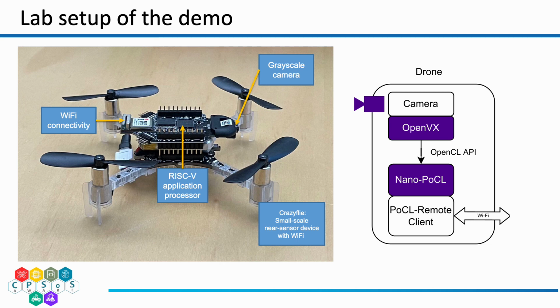The whole application logic is executed on the RISC-V core on the AI deck. The application consists of an OpenVX program implemented in OpenCL. The Nano-PoCL OpenCL implementation pushes the OpenCL commands through the network for remote execution.